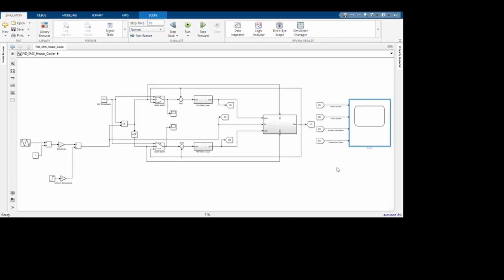As you can see, it is behaving as a second order system up until here, but as soon as the error clamped the input, that's what I've been trying to tell you, it started sliding over this surface. That's why it is called sliding mode control of our heater and cooler. So as we can see, the heater part of the section works very well.